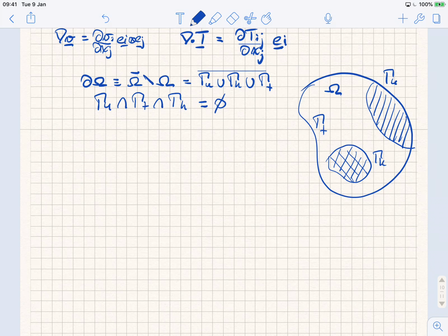So we are ready. So what is a strong form? Now that we have our conventions, a strong form is, well, again, we're going to list the different components of our equation. We talked about the conductivity. Well, the conductivity in higher dimensions is actually a tensor.